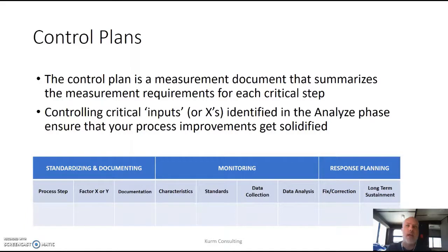So if it's something like a setting on a machine, know your limits. So it shouldn't be above this amount or below that amount, okay? And then you also want to state what kind of data needs to be collected here. So maybe once a day, an operator's got to go out and collect something. So we would want to identify the data collection method, right? And what happens, and maybe that's outlined in your procedure, but it's useful to outline it here in your control plan as well.